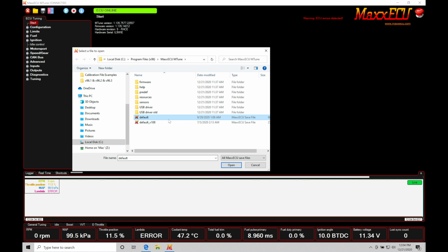That is nothing specific to any particular engine. It won't start up the vehicle I'm working with here. I'd have to configure it to all the details for that vehicle. So the cam crank sensor information, all of the air temp and coolant temp information, calibrating the throttle position sensor, making sure the map sensor is set right. So there's a lot of details that have to be gone through in order for this to fire up.